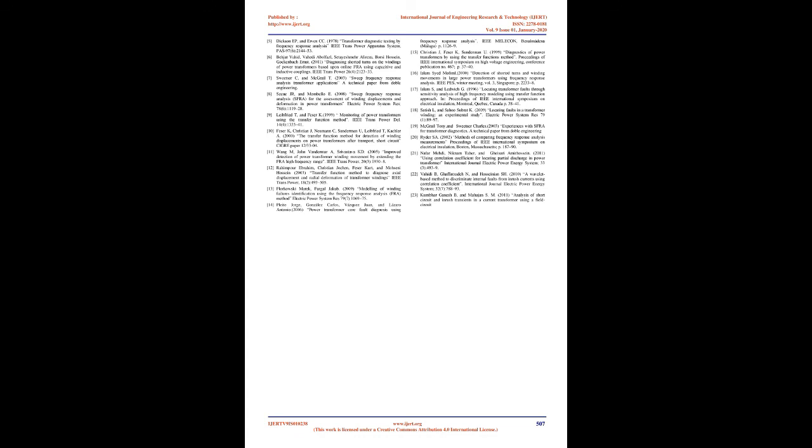It was found that the differences between the normal and faulty responses of the transformer's windings damaged by interturn faults was more reflected in the spectrum deviation as compared to the correlation coefficient. Based on the findings, the SFRA method can provide effective interpretation of transformer performance, in terms of early fault detection.